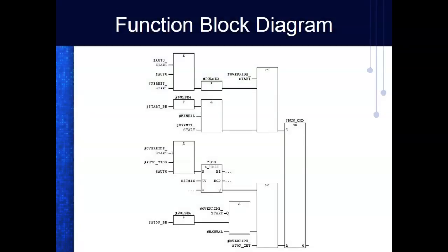This is function block diagram. This basically is, if you came up through digital and electronics, this is digital. We have AND gates, we have OR gates, logic functions, except they use the IEC, the International Electrotechnical Commission, symbols. These are ISO symbols. Over here, if you do take digital, we use what they call ANSI symbols, which is the American National Standards Institute.